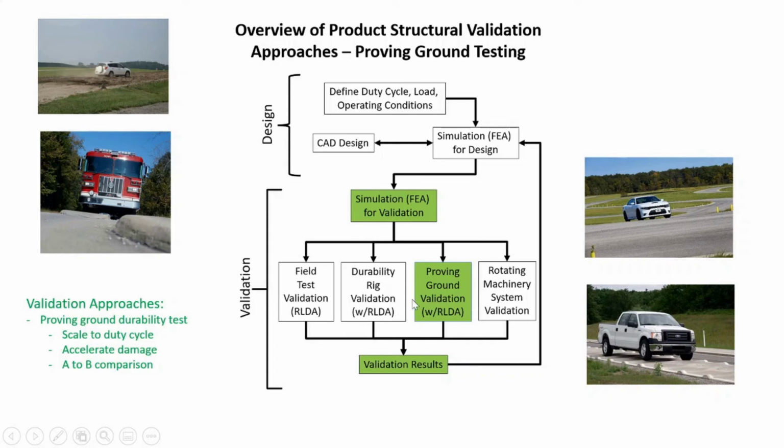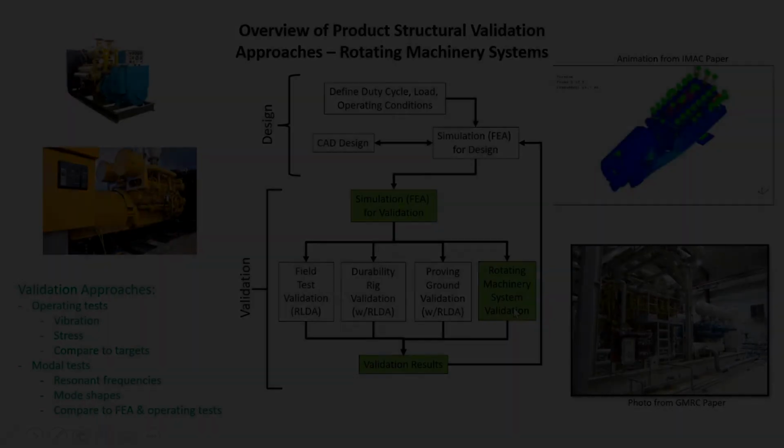Or it could be used in supporting rig validation testing, where the hydraulic rig that might apply loads to a structure in a lab is used to do an accelerated damage type of testing. And another thing that's often done on a proving ground is an A to B type comparison, where perhaps a known design with a known life is compared to a new design over the same type of course. So that becomes a comparative type of analysis.